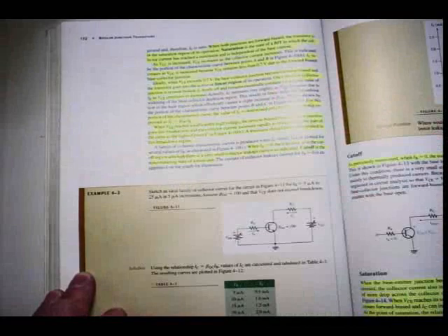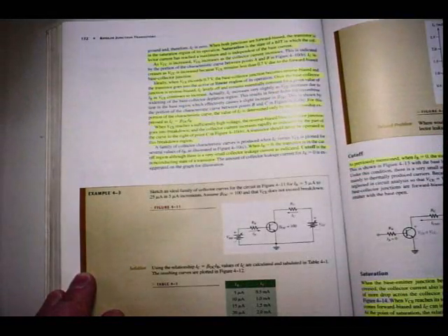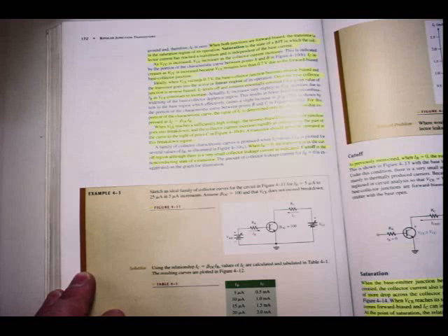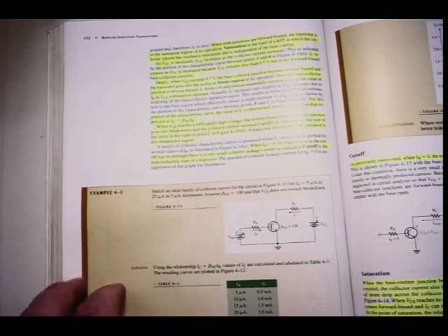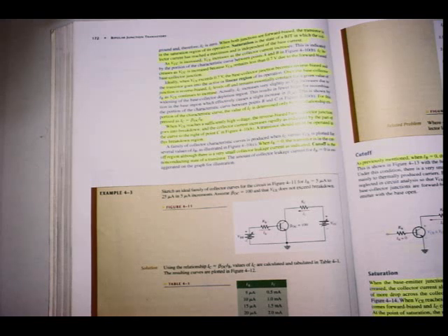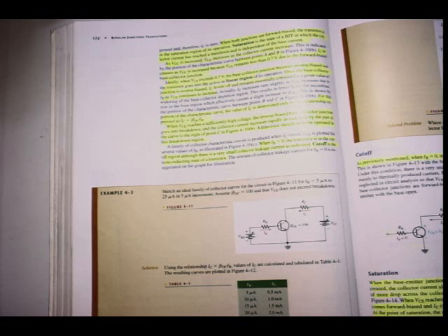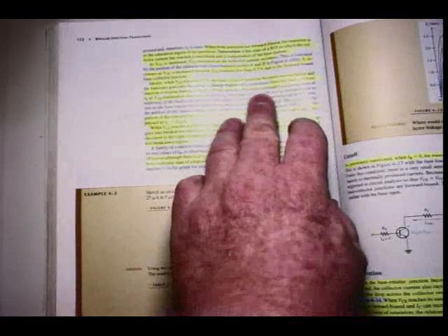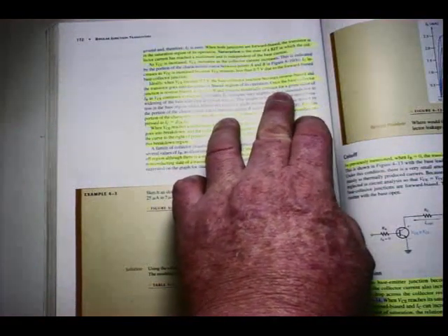Ideally, when VCE exceeds 0.7 volt, the base collector junction becomes reverse biased and the transistor goes into the active or the linear region of its operation. Linear region of operation means that is the area where I'm going to use the transistor for amplification. When IB is equal to 0, in other words the transistor is off, or when it goes into maximum current, it's in saturation. Those are the two areas I will use it as a switch. So it's either in cutoff or saturation, the switch is off or the switch is on, or in the area in between I will use it for amplification, which is called the linear region, but we will discuss that in much detail as we go along.